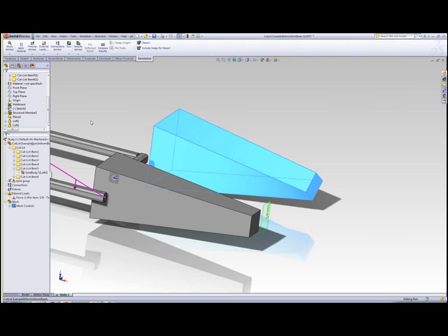The simulation interface will give you a little warning that recommends you to not treat a body as a tapered beam. So you will see that behavior in case you are running a little bit closer than the simulation study would like for you to treat certain solid bodies as beams.